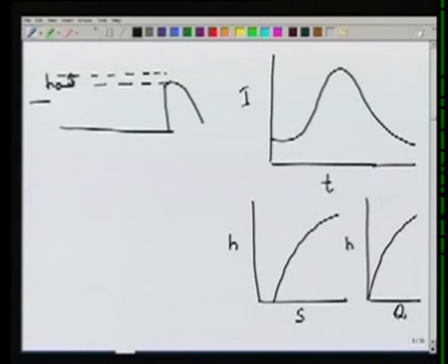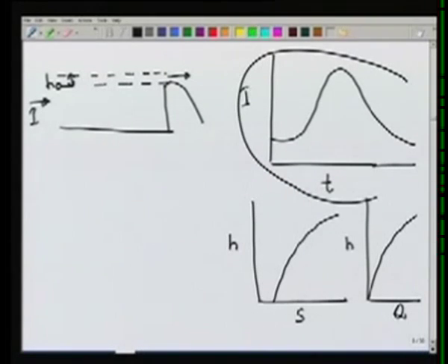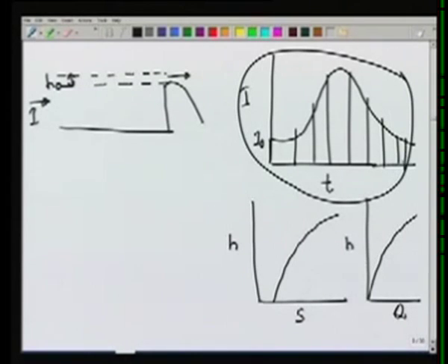And then the inflow comes, and we want to route it through the reservoir. The inflow hydrograph is given as this. So at time t equal to 0, we know what is the inflow, I0. In fact, the inflow hydrograph is known for all times, so at any time we can find out what is I from this curve. So if we take this time step, we can use different methods to solve this equation.